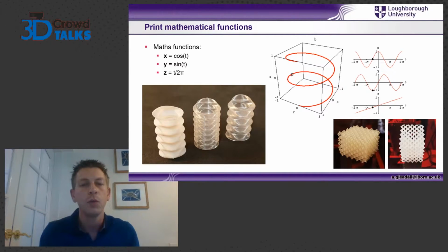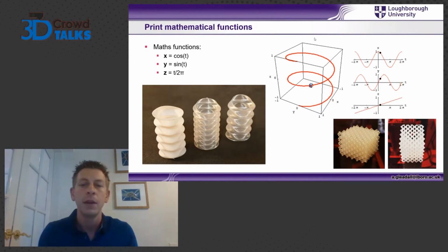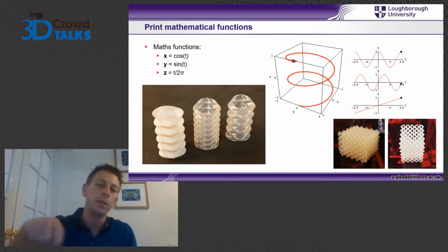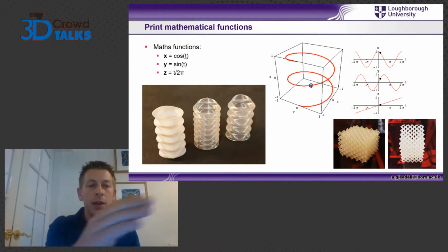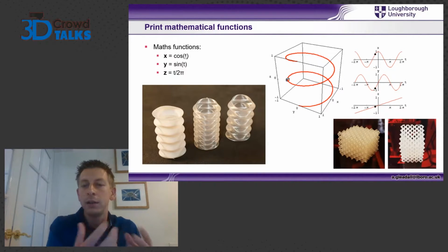Then going on to more advanced things, if we're defining the toolpath, then an easy way to define toolpaths is through mathematical equations. So you can see this spiral image on screen with the little block moving around it. The XYZ equation for that is just written on the left-hand side there. And T is just a number that's going to go from 0 to 1. And when it's 0, that little block is at the very bottom. And when it's 1, the block has moved all the way around up to the top. So for T set to a value of 0.5, the XYZ values would be the location on this red line halfway up. So we can program a really nice intricate toolpath.